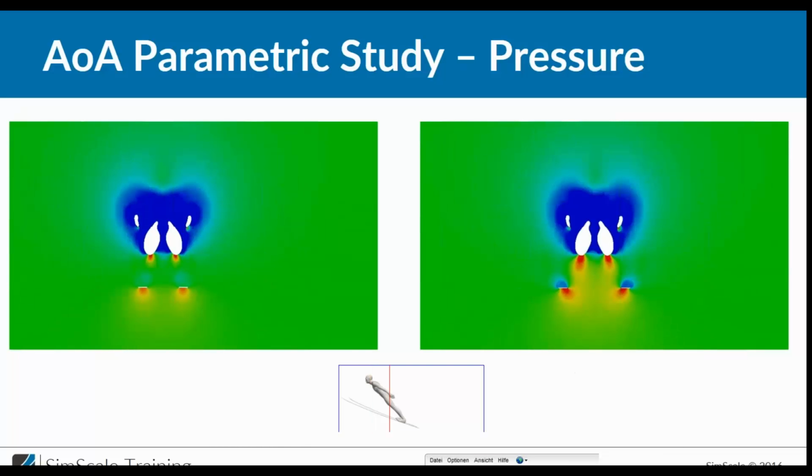So here again, I think it's pretty much the same effect, Akram, right? Since the skis are near the body of the ski jumper for parallel legs, you have much more interaction and pressure exchange between the skis and the body, and therefore the low pressure region here is again smaller, and also the high pressure region. You can imagine it like, since the distance is smaller here, you have more exchange between the areas. Yeah, that's right. I totally agree.